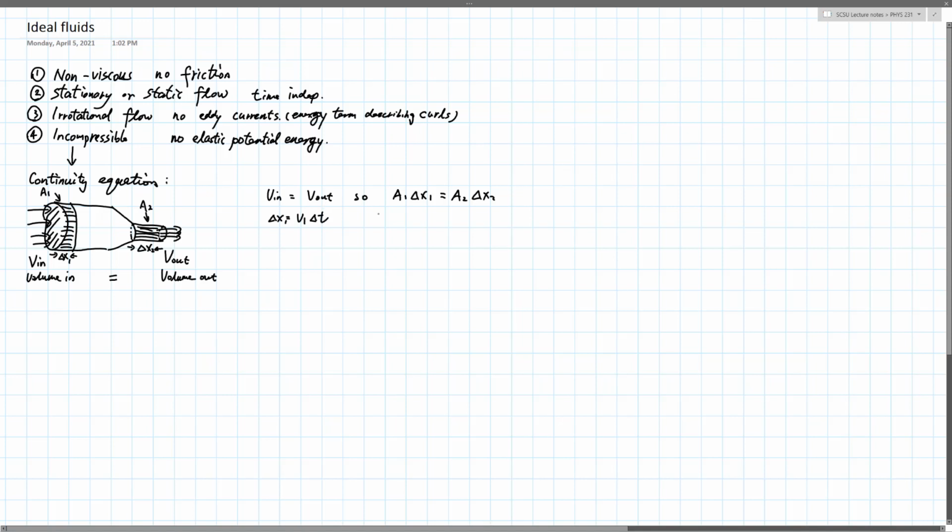During that same period of time, the back surface right here flows forward into the front surface, and that translates into the volume that has flowed through, right? This is the back surface flowing this much distance at a different speed. We don't need to assume that water flows at the same speed. You have that experience: if you squeeze this end, you're going to have a jet of water.